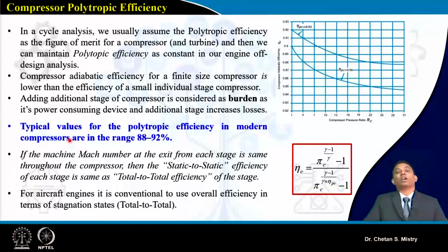And when we are talking about commercial aircraft, where efficiency is a major concern, and fuel economy is a major concern, you are restricted in increasing the number of stages. Even for military applications, the length of the engine will increase, and we cannot accommodate that engine within the fuselage that is provided for military applications.